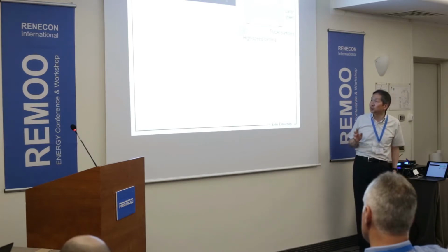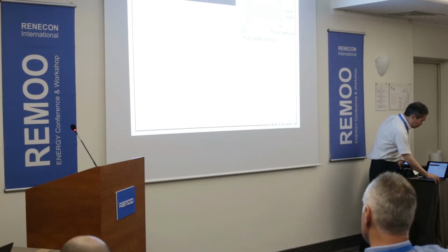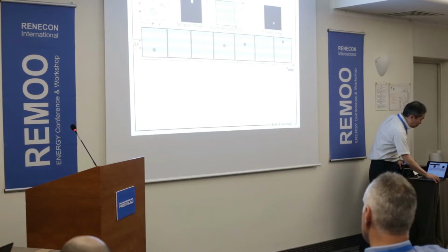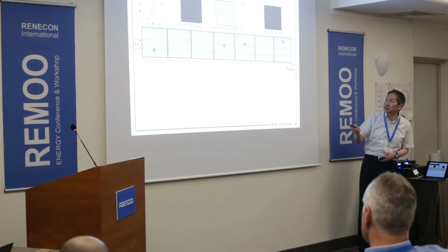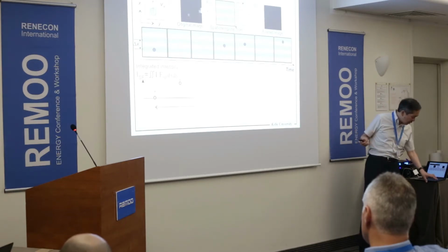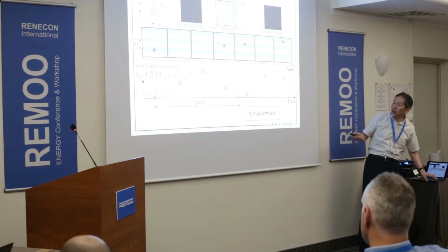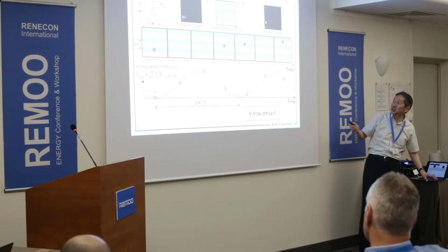I'm not going into detail, but this method is really good just by making the mask of the image in this interrogation area. We put masks here, and then we can have this kind of oscillation of the intensity of the brightness of this image, from which we can evaluate the velocity of the seeding particles.